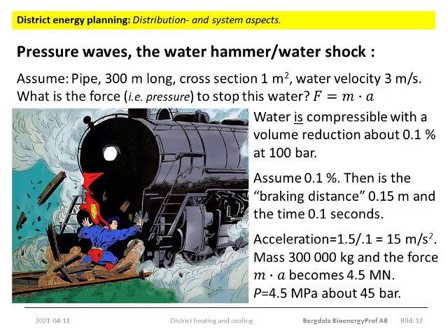In most cases, we consider water an incompressible fluid. But really it is not. At 100 bars the volume of water is actually compressed, and the volume is about 0.1% smaller than at 1 bar. So if we just assume that the pressure becomes 100 bar and we have a volume reduction of 0.1%, then the total water volume will experience a reduction in length equal to 0.3 meters. The center of gravity will travel only half that distance, so it will travel 0.15 meters.